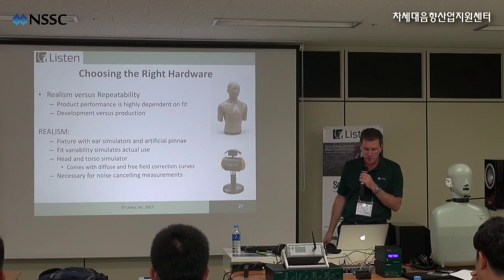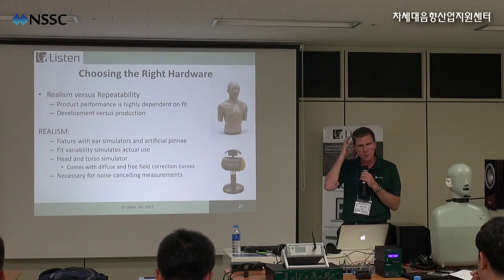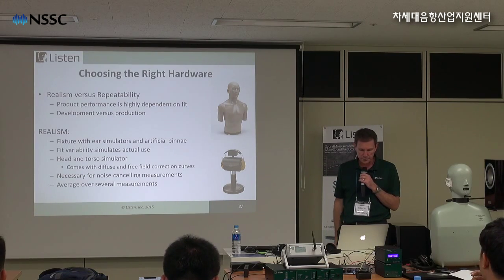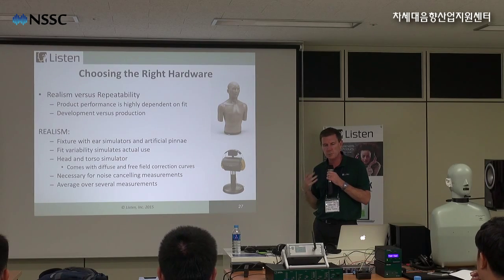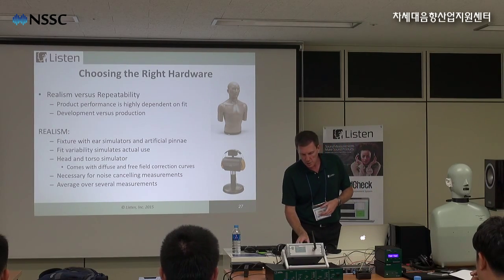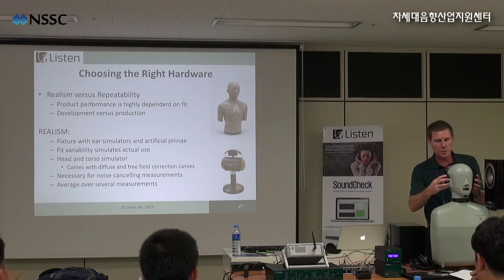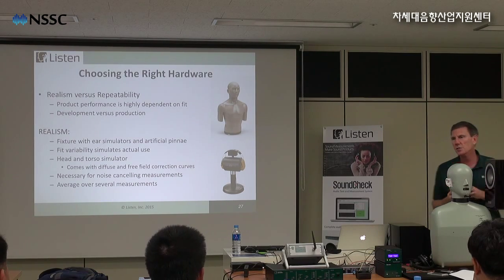And again, if you're doing noise canceling measurements, you need to simulate the real pinnas and ear couplers, or ears, I should say. And typically you want to do several measurements because positioning matters. So you might do one measurement like that, then adjust it, take it off, and put it back on. The reason is that the positioning is never going to be identical, just as in real life.